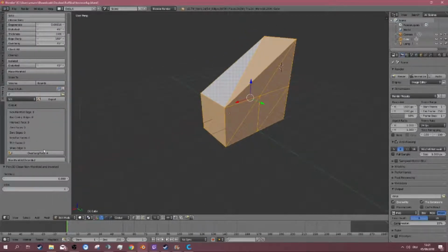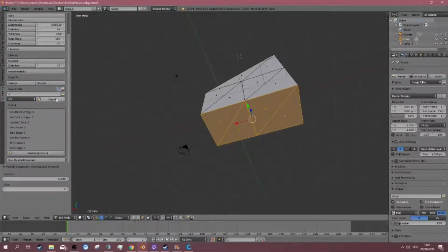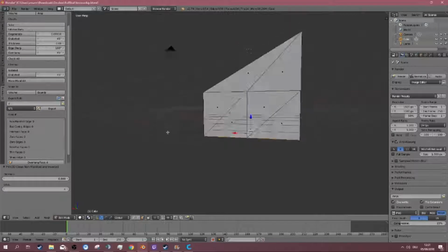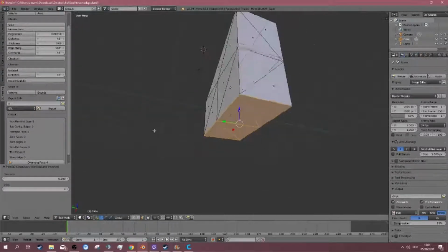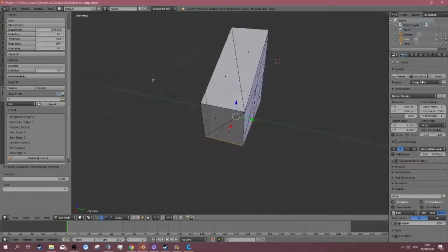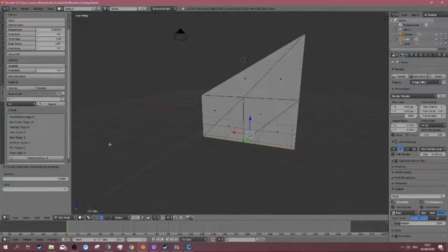It shows an overhang face, which is on the bottom, which is over 90 degrees, I guess. Overhang 45 degrees. Yeah, it's the bottom, for sure. But it shows you where you have bad edges or zero faces. Zero faces is actually also a good thing to check if you're making something.